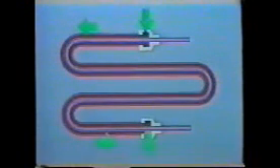But now, let's take a minute to review what we've seen in this segment. In a shell and tube condenser, the cooling water flows inside the tubes. Refrigerant vapor flows around the tube. As the hot vapor comes in contact with the cool tubes, it condenses and falls to the bottom of the tank. In a tube-in-tube condenser, refrigerant flows through the outer tube and water through the inner tube. The refrigerant vapor is cooled both by the water and by air flowing naturally over the outside tube surface. Stop now and review these condenser designs.